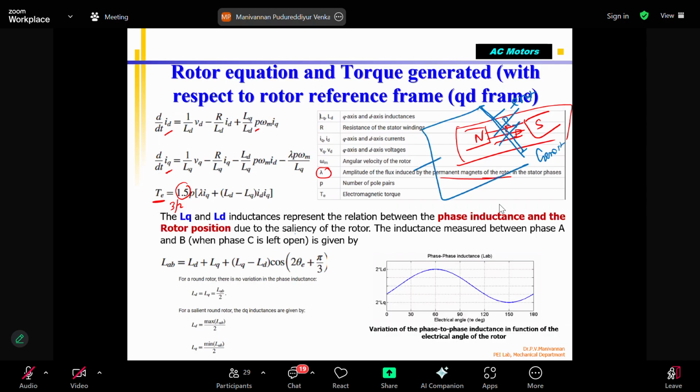In this one, plus minus, there's a current flowing. Magnetic flux, that I am supplying current. Automatically, one more magnetic flux is created due to current flow in the wire. Then this magnetic flux interacts with the already existing magnetic flux. This we call a field magnet or stator magnet. This is called a rotor magnet or armature magnet. So there are two magnets, they interact, and the force is created.